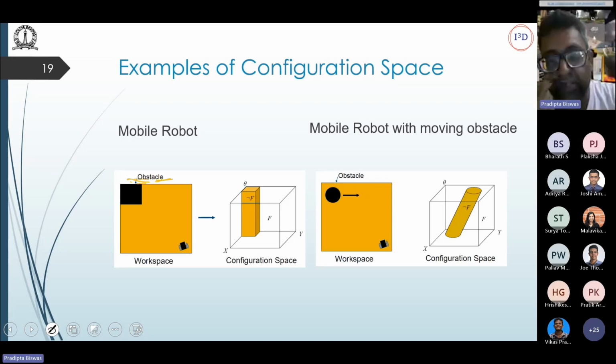Of course, this is not defined arbitrarily. So there is a way of doing that. There is a specific chapter or lecture or session on obstacle representation in configuration space, where for simple obstacles, we can use geometries to represent that. For more complex obstacles, it becomes more complex. And on Thursday, we will discuss some algorithms called sampling-based algorithms, where we need not explicitly write equations of the cylinder or parallelepiped here. Rather, we will use some sampling strategy to only know whether a robot can go to a particular point in the configuration space or cannot go.